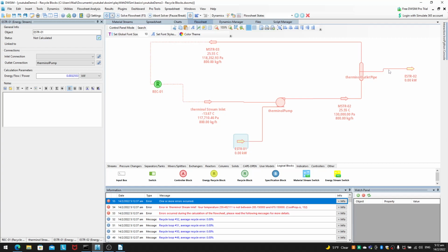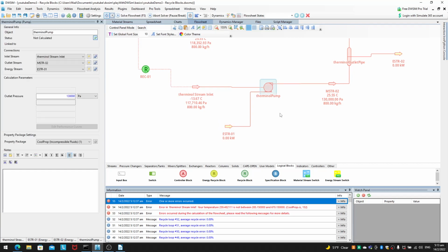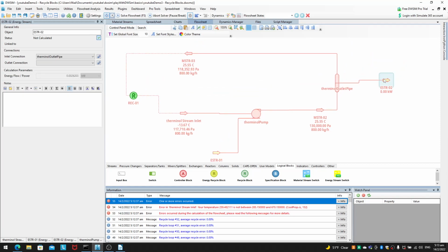So we have a similar problem to what we had just now. Basically, we set this in terms of a thermal energy balance. We have a set amount of energy going into this pump, in terms of thermal energy, and then another fixed set of thermal energy coming out of this pump. If those two don't balance, then technically this system will keep accumulating heat over and over again as we go through the iterations. Then you will have this non-converging temperature issue as well.